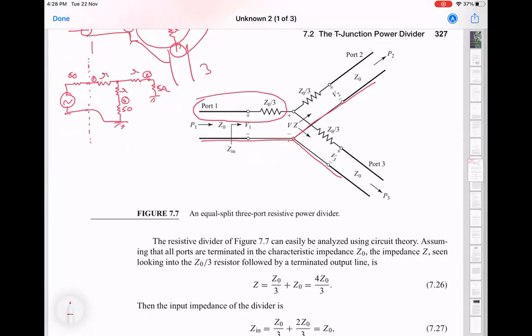So what we have here is these two branches here and here, they are in parallel, right? So that means the resistance from this point to ground is going to be 50 plus R over 2. And then this little r here is in series. So that's the total resistance. So in this case, because there are only lumped element circuits involved, the DC analysis and the AC analysis is exactly the same.